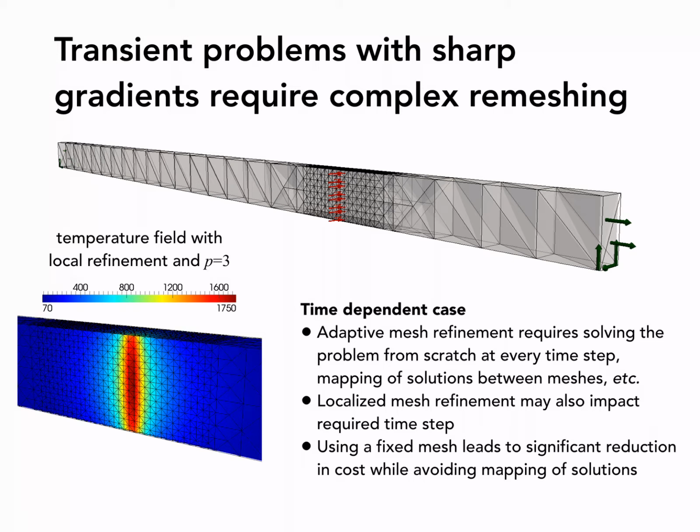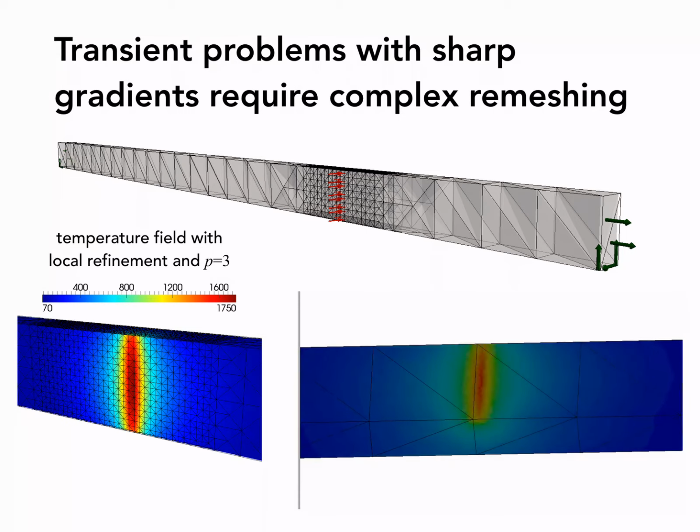And the solution here is not even standard FEM. It's using something called the P version of the finite element method, which is something that we'll also look into in this course. You see that the solution was obtained using a polynomial of third order. And so you can think, well, how about we just use enriched formulations for that? Well, you can actually do that, and then you see that you can track a very sharp gradient through that beam, without having to refine at all, because you're actually adding a function that captures the sharp gradient inside those elements.